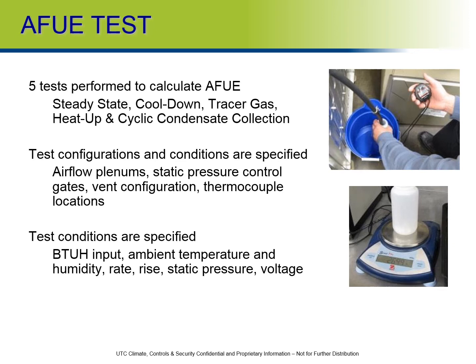So for instance, if you have a single stage 95% high efficiency gas furnace, it may only achieve that 95% AFUE rating in the 120,000 BTU furnace size. But since they achieved it in that furnace size, they are allowed to claim that AFUE rating across the board on the entire line of single stage 95% furnaces, or say, model lineup.